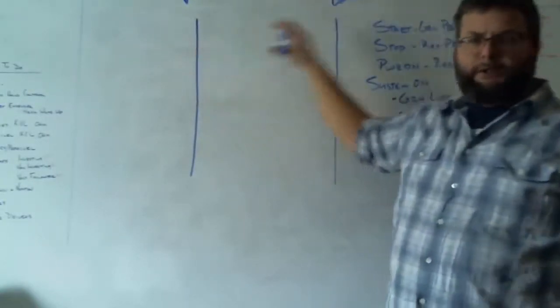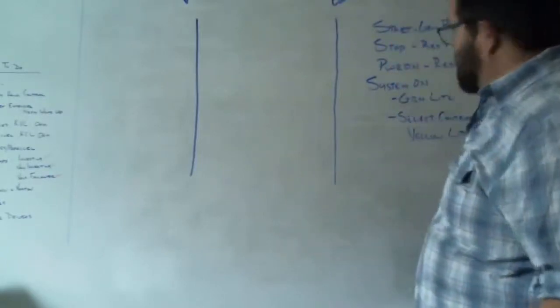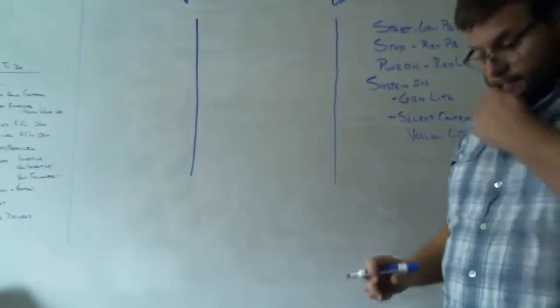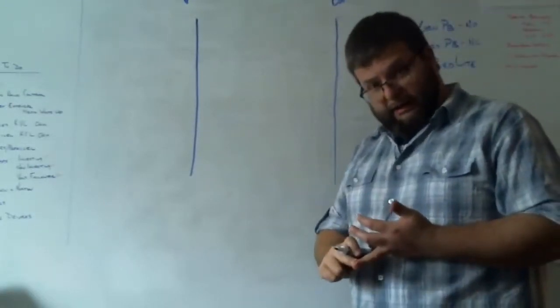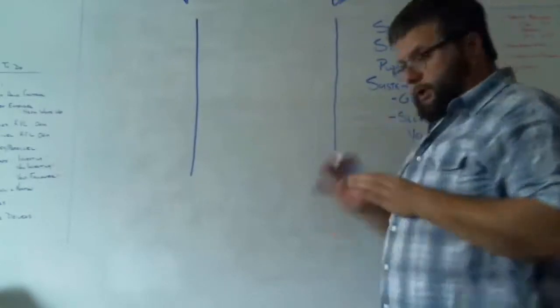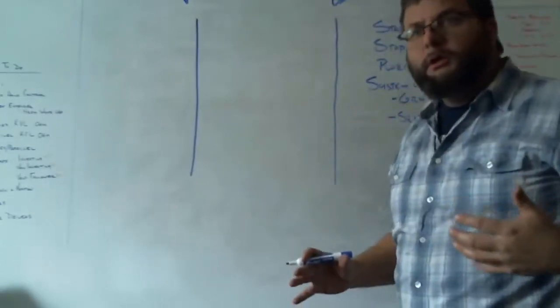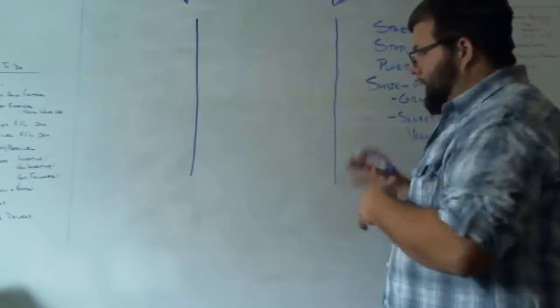It can be AC voltage and neutral, depending on what voltage we're running. That is going to be dependent upon the outputs that we drive. So we have relays, lamps, or motors that we have to drive. In this case, we're just going to assume they're all the same voltage. And if that's so, we're just going to have a voltage and a common.